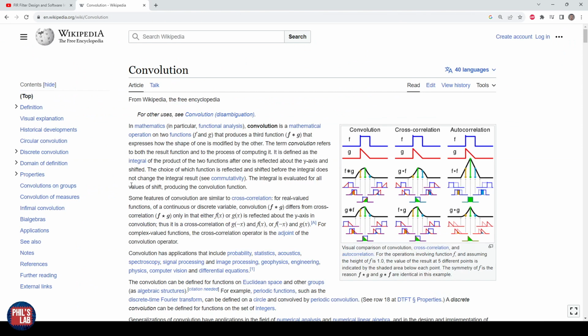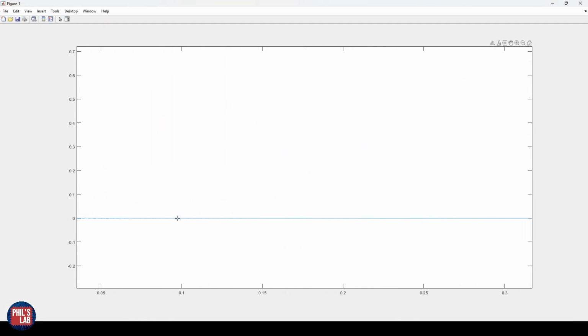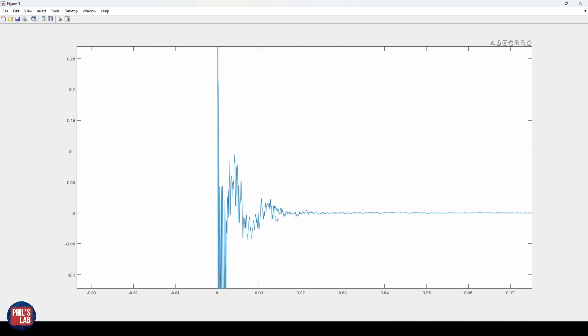The main idea behind FIR filters is convolution, and this is a fairly costly operation, and it's more costly the larger the arrays are. And this, of course, leads directly back to the impulse response. If we use a very, very long impulse response, which we have to convolve with our input signal, which forms the basis of the FIR filter, then of course this will take a lot of time, which probably won't work in a real-time system. So we will have to truncate the impulse response quite significantly to make sure this can run in real time and we don't run out of computation time.